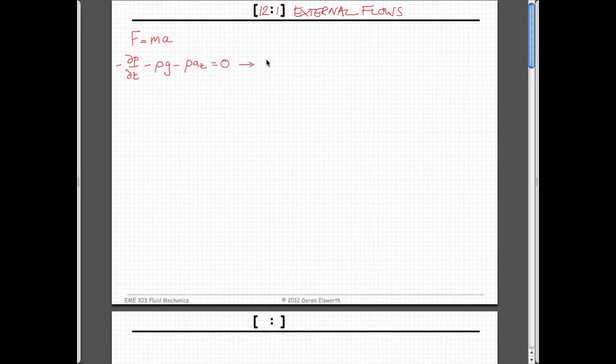And if you recall, we used this to get, for a static fluid, this expression, which is this term here, which says that pressure changes linearly as you go down within a fluid. And ultimately, this also gave us what? This gave us the pressure is equal to P0 plus the depth times the unit weight, right? That's basically that expression. We use this expression to derive another equation when the fluid wasn't static. So this is static. We used it to derive another expression, and you will recognize this other expression.